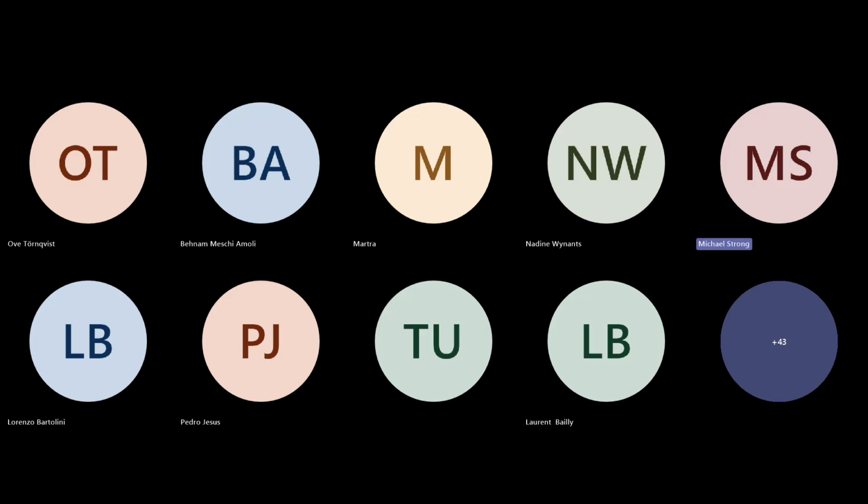Sure. So with conformal coatings, you haven't mentioned thickness. I'm assuming that the standard 25 to 75 micron dry film thickness is what we're aiming for across your different chemistry types. Across the different chemistry types, yes. But with silicone, for whatever reason, they've upped it to 3 to 8 mil. And I think they did that because some of the coatings are 100% solids. Okay. But typically with your IPC standard, the adoption is 1 to 3 mil dry film thickness, correct?